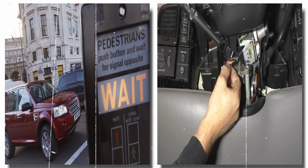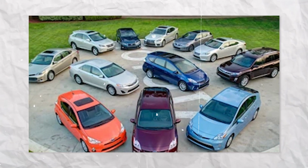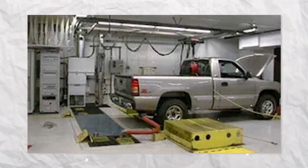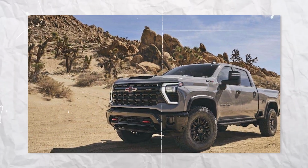The idle will hunt and search as the ECU relearns proper idle control. This is normal. Let it stabilize completely before you touch anything. Once the idle settles, you can turn on accessories and make sure everything works properly. Check that your radio presets are erased. Check that your seat memory positions are gone. If those items reset, you know the battery disconnect worked completely.